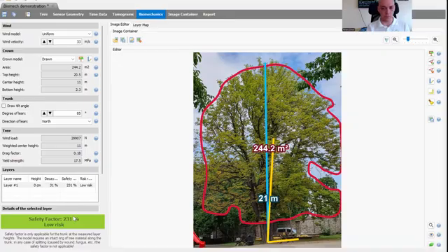The EN standard uses the base wind velocity that is defined by the national annex, and it's for a territory. But the uniform model is just using the drag equation from physics and uses the maximum wind speed for which we calculate the wind force. And for this reason, you see a much higher wind velocity. Very often I see the mistake made by users that they use the highest wind velocity for the Eurocode model. That is a serious mistake, and you should always consult your national annex and the base wind velocity defined for your area. Ferenc is going to show you this later.